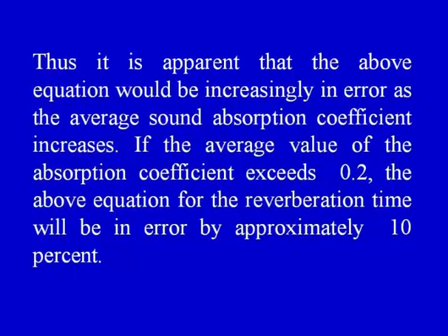Thus, it is apparent that the above equation would be increasingly in error as the average sound absorption coefficient increases. If the average value of the absorption coefficient exceeds say 0.2, the above equation for the reverberation time will be in error by approximately 10%.